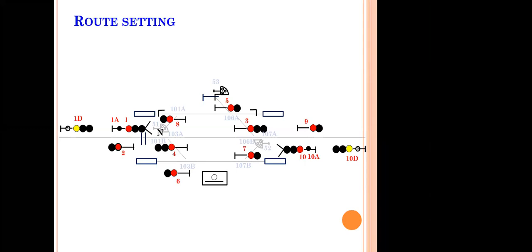What do you mean by detection? Detection means an electrical connection which will ensure the point is in normal. Many of you might have traveled by AC 2-tier, AC 3-tier, AC first class or by flight. You will have an indication for the washrooms, whether occupied or free. Those indications are controlled through a knob inside the washroom. As you close the door, the contact is closed and the occupied indication becomes visible outside. That is what is called detection.